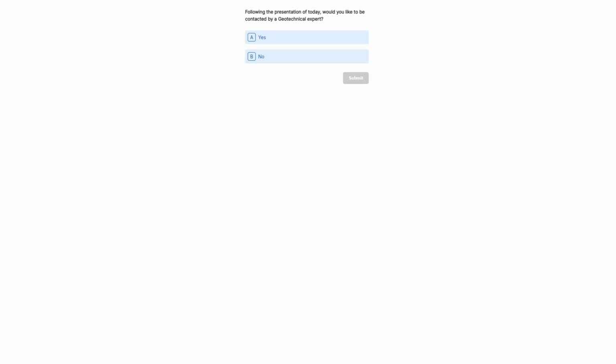The second question is where to use groundwater flow and where to use phreatic. It's a difficult question. Some people say it's better to use groundwater flow all the time because it is the most accurate way. Yes and no. Yes, it is the most accurate way as soon as you are convinced that the steady state situation is the one which is relevant for you. There are situations where this might not be, especially when you work in relatively impermeable materials. The steady state might not be the most relevant case, and sometimes you might be better off using a phreatic level with conservative assumptions rather than doing a completely unrealistic assessment of the water pressure corresponding to the steady state. That would be my answer to that question.